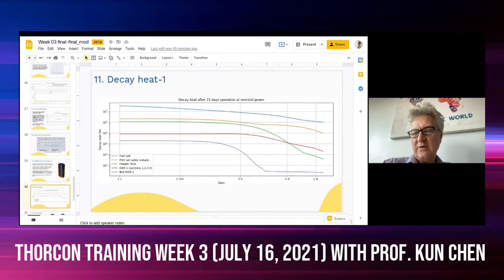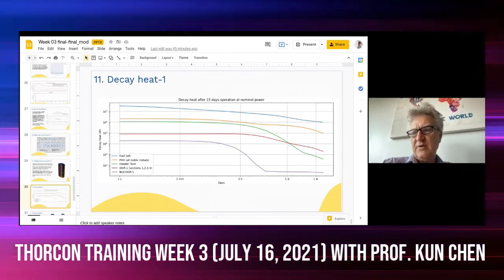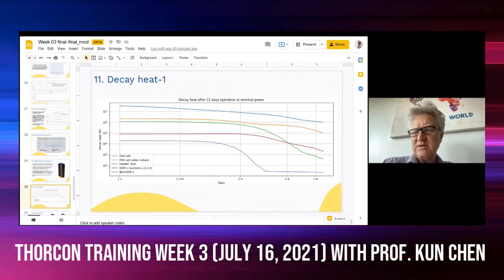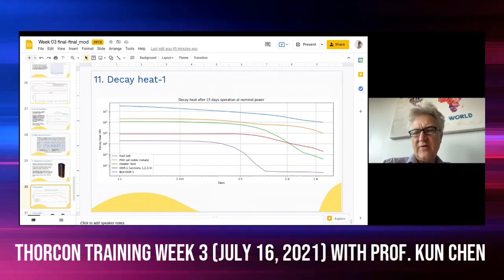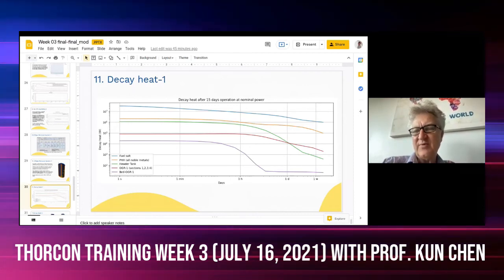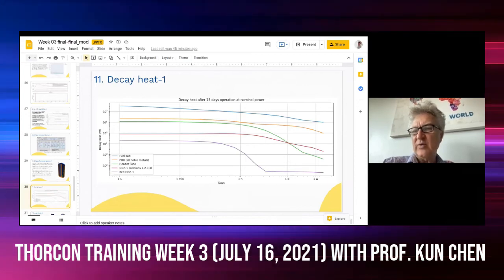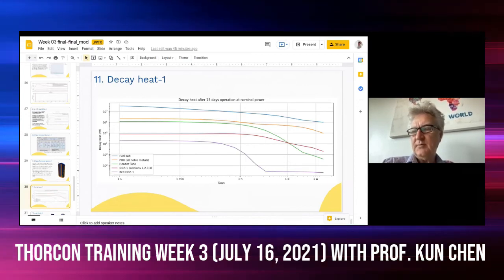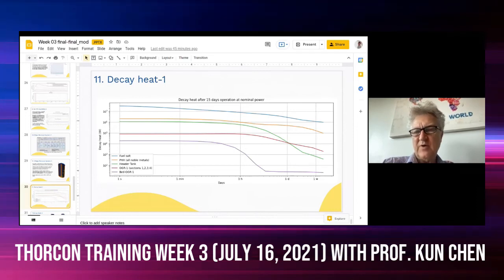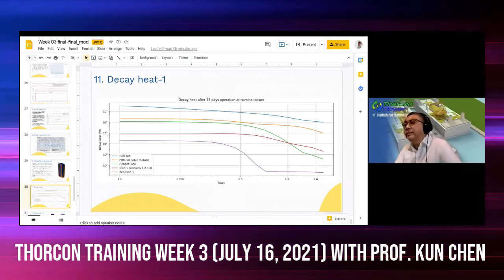We made the reactor larger diameter in order to accommodate it. The aspect ratio, I think, is like 1.6 to 1, and I'd rather have a 1-to-1 aspect ratio. That would be a preferred choice, but we're still within a reasonable range. And yes, the volume is roughly the same as the old one. That dictates the graphite lifetime.